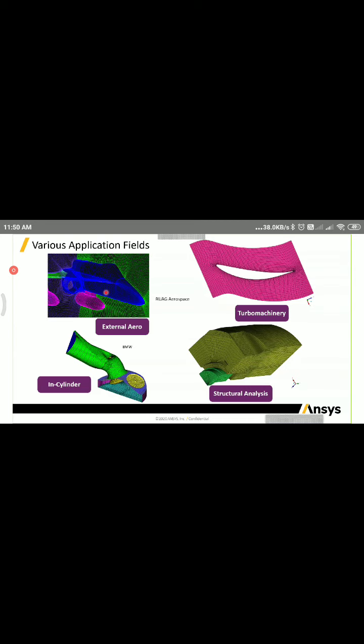Then there are different advanced controls actually to capture the mesh. Generally, as this is a block approach, it depends on how the blocks are going to capture your geometry. So you have the different options to create O grid, L grid, C grid, and it depends on the shape. If you have a complete cylindrical shape, you can go with complete O grid. If you have something like a wing only, it will be a C shape. If you have something which is a quarter like this, it will be an L shape. So your O grid will be L type. Here it will be C type.